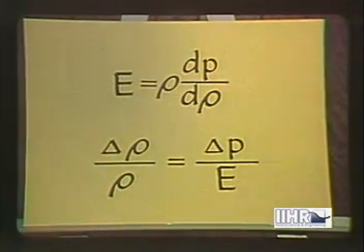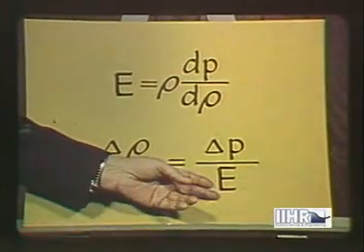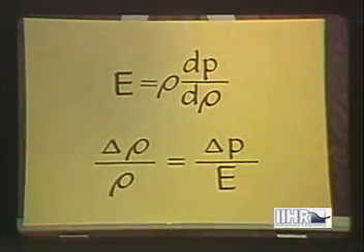Even at the bottom of the ocean, however, the relative increase in the density of the water is only a few percent because of the great magnitude of the elastic modulus. The density of a gas, on the contrary, can vary from that of its liquid state under very high pressure to its standard value at atmospheric pressure. And we know that the density of air varies from its standard value at the Earth's surface to essentially zero in outer space. Under non-static conditions, on the other hand, the effect of a local change in pressure is to